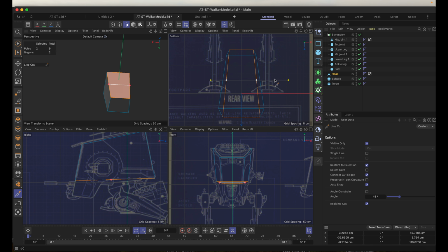Okay, and so currently that's not exactly where I would like this to be cut. What I would prefer is to slide this thing so it's about right where that bend starts or where that edge starts. So you can see I've got one there. So now I can come over here, I can click and drag, I can hold down shift and snap it into place. And that's right where I want my cut to be.